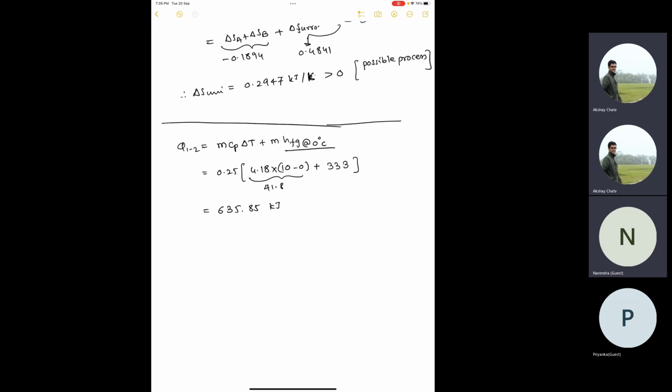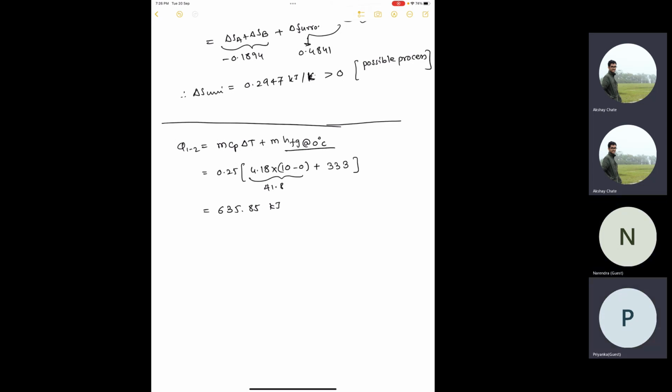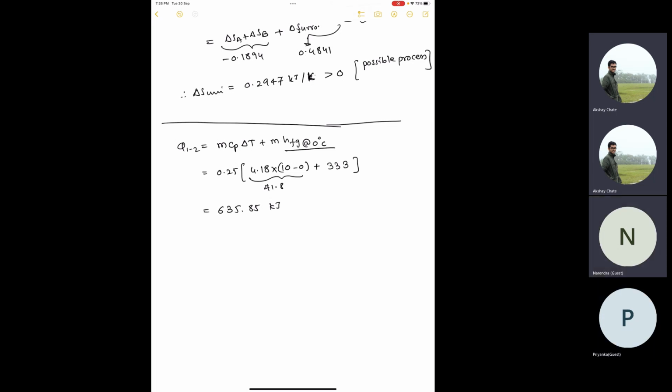Because here, Priyanka, you are converting the solid to water, ice to water. So it should be the latent heat of fusion. Steam table is not right because steam table is for liquid to vapor. Here we are using ice to liquid, right? So it is fusion. And this 2501 value, which Priyanka told me, that is the latent heat of vaporization. So, okay.